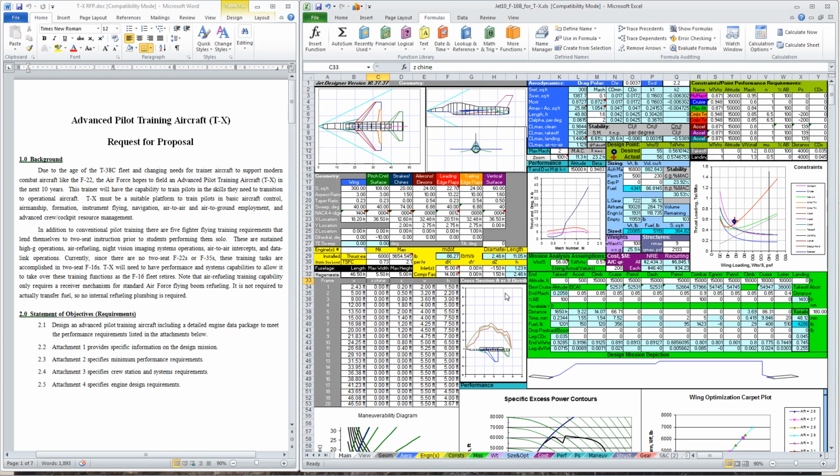All right, well, this is really a pretty nice solution here. We have a solution to the sizing equation as well. And so at this point it may be appropriate to see if we can optimize this wing a little bit. We've got, as I say, a pretty well converged solution at a fairly small engine size. Let's see if we can help it by changing the wing.